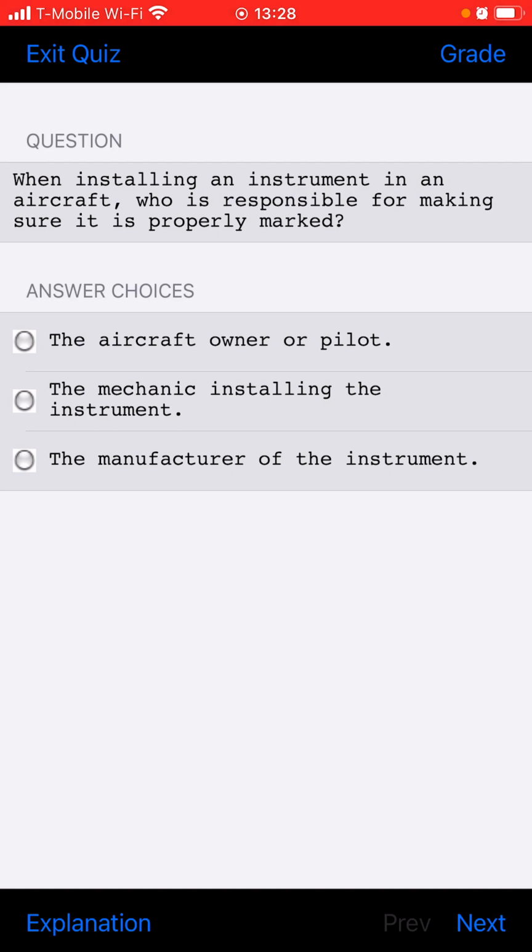Describe the operating principle of a continuous flow oxygen system. High pressure oxygen flows from the storage cylinders to a pressure regulator, where its pressure is reduced, and then to the mask outlet whenever the system is turned on.